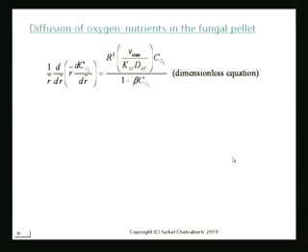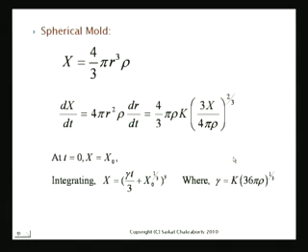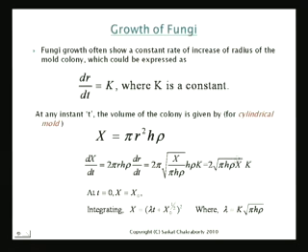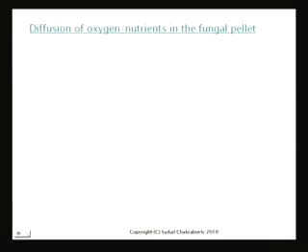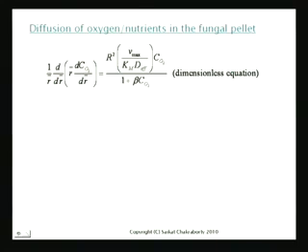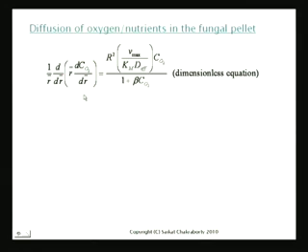So this is a cylindrical model that we are taking, a cylindrical fungal pellet. Let me just go back. This is what we did for the growth process, but this growth process is not a complete growth process, the reason being that there is mass transfer resistance offered to the substrates. The substrate can only reach from the outside, so that is a major difference between this and the single cell model. So this is a substrate. I refer to that as oxygen, but it doesn't have to be oxygen. It should be everything else: oxygen, carbon dioxide, carbon, hydrogen, everything put together. But let's assume it to be oxygen.